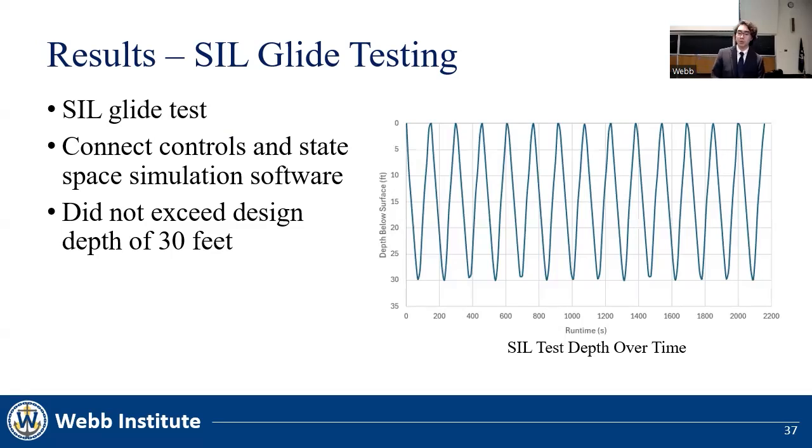The glider controls were tracked over this test period and changed states and moved as expected in response to the glider motions. While a scenario with 0 lateral motion of the AUV is not typical, this test demonstrates the effectiveness of the control system for the AUV's glide cycle.